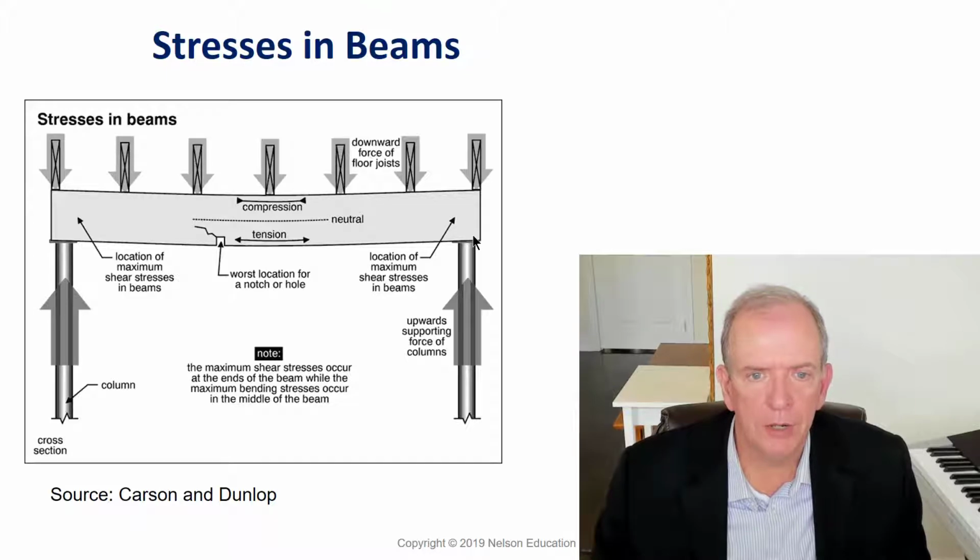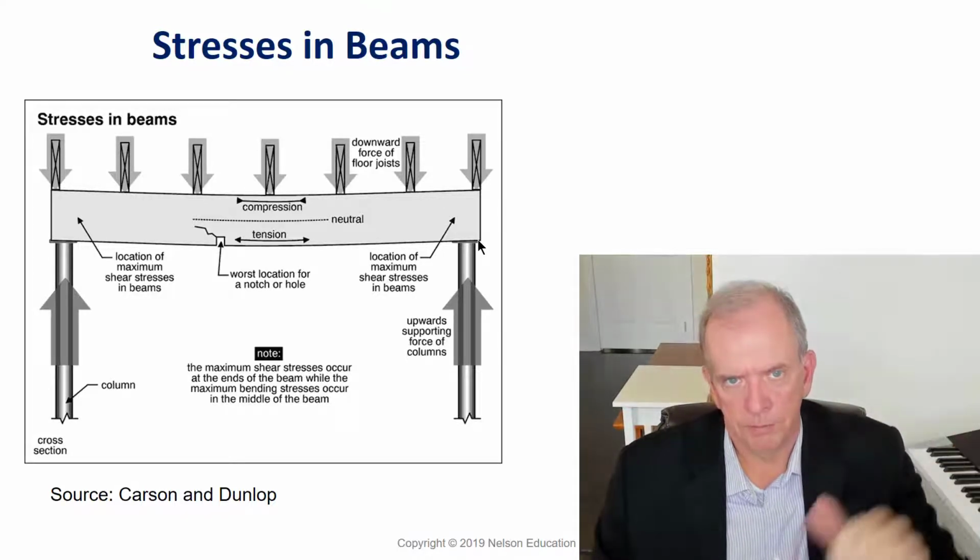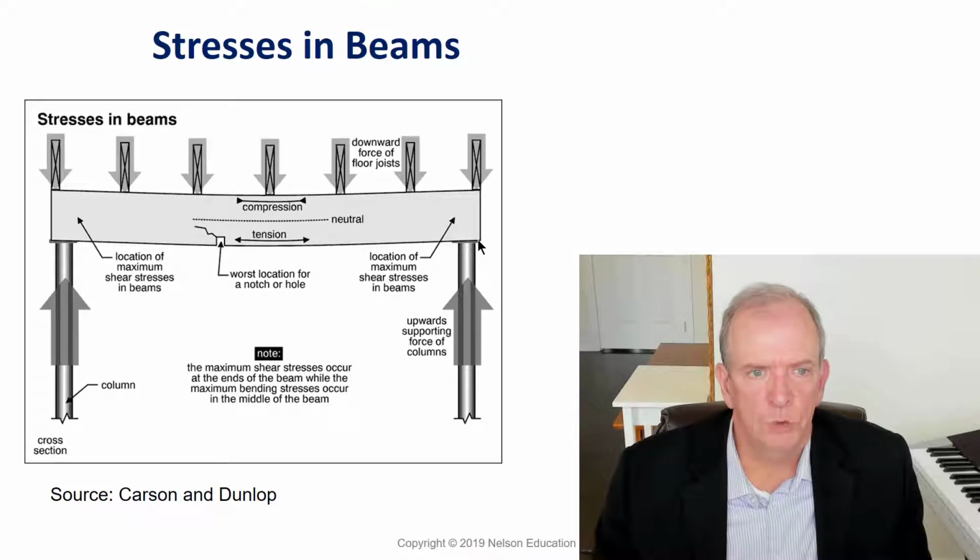And if we didn't have enough bearing, if this was a very small bearing, then the weight is not being distributed over there. That could cause more problems in the structural integrity of the building. So that's why we have minimum bearing for a joist, 1.5 inches or 38 millimeters. Minimum bearing for a steel beam, as an example, 89 millimeters or 3.5 inches. And like those varying requirements that we just talked about with lumber. It's good to understand these forces. Also, when you talk about concrete, reinforced concrete, it's good to understand too.